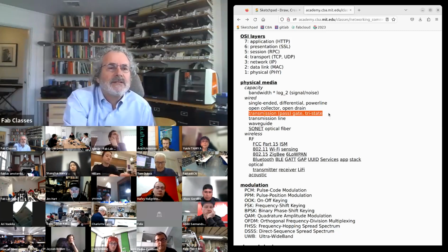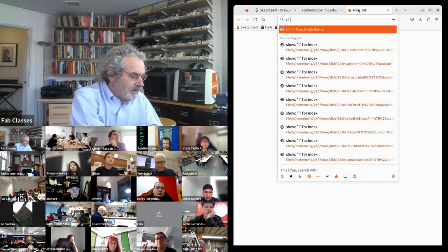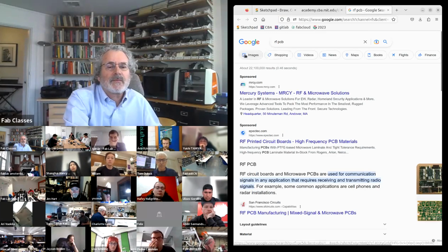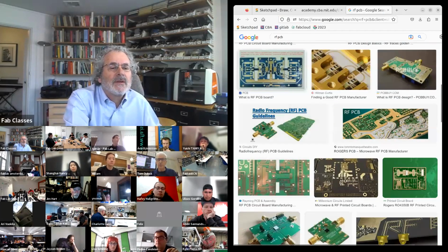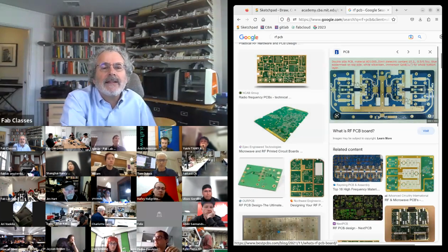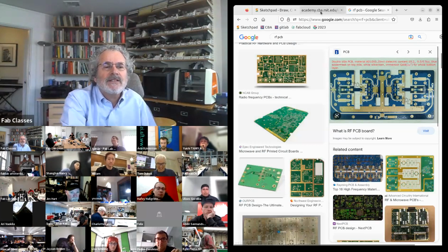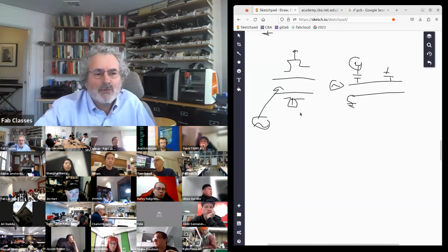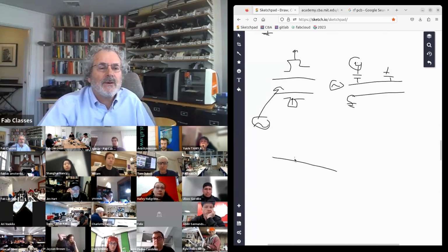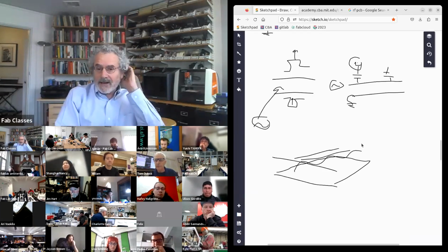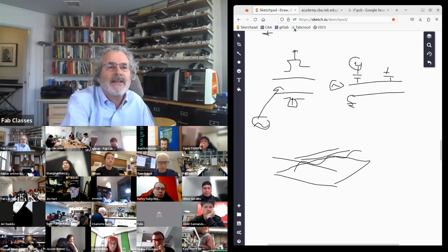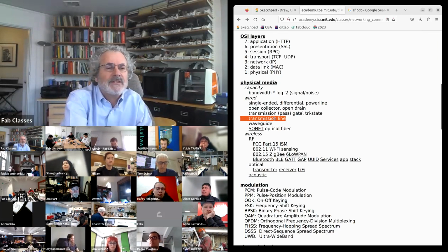Then at higher frequencies, if you look at an RF PCB, at high frequencies, you'll see these fat looking wires on the PCB. Those actually aren't wires. What those are is what's called transmission lines, where you have a line that looks like that, and then on the bottom of the PCB, underneath it, you have a ground plane. And what's actually happening is you're guiding a wave that follows the line. So the signal doesn't go through the wire, it actually gets guided by it. And so that's in high frequency design.